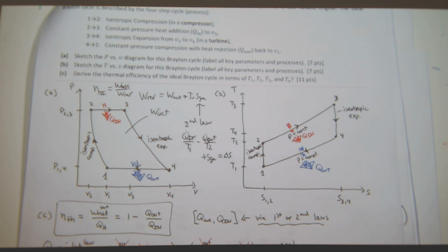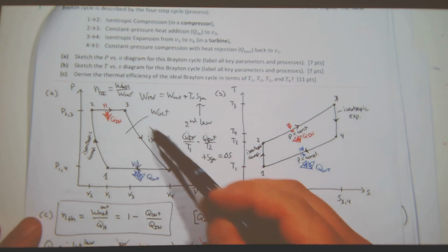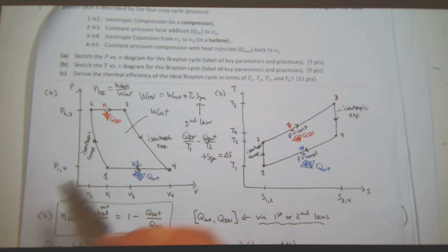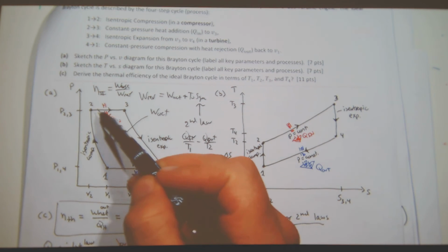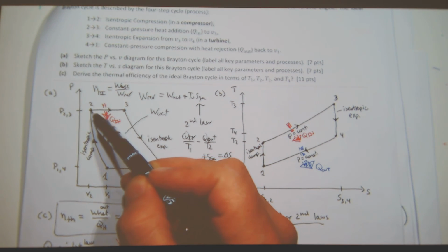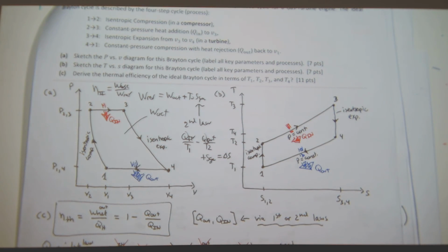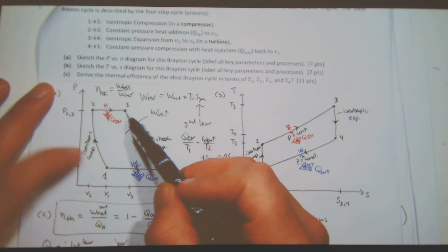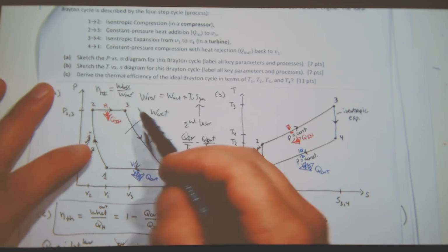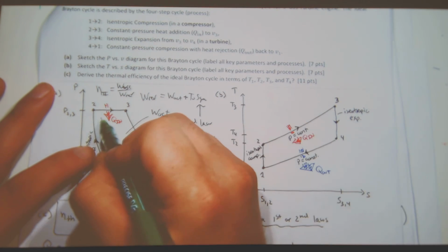Yes? So what does happen to these graphs if there is mass loss? Let's just think about what happens to this graph if I have mass loss. Okay? This one right here. Say I go through one cycle, and at some point I get to this high temperature, and I start getting a crack in the wall, and there's mass loss. What happens? Your volume goes down. Pressure goes down, and let's just draw it in green.